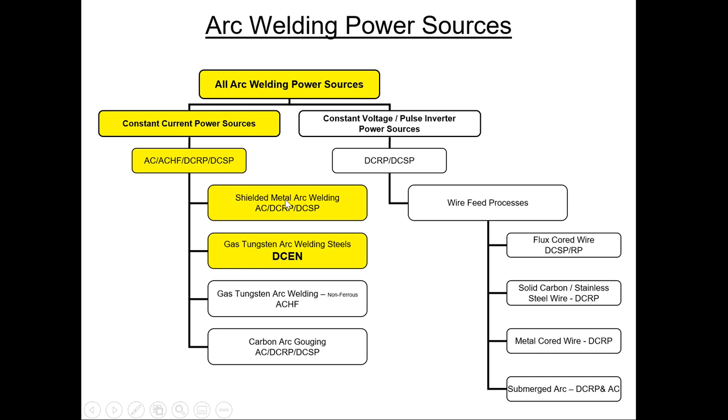Now I've left a couple of options open here for us in tool steel. Shielded metal, which I might want to use. I might have mentioned I'm a big fan of using shielded metal stick electrode for joining because it gets a lot of material down in a hurry. It takes forever to get the shielded metal with no advantage if you wanted to try to take the softer material, the underlay material, or what we know as the joining material, which is usually high in nickel. Gas tungsten is our goal, and we run it in direct current electrode negative, also known as straight polarity.